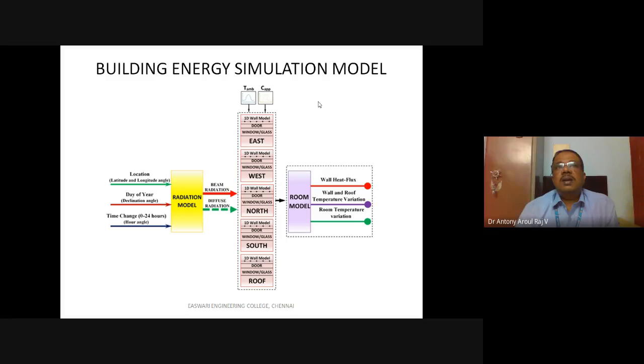So this absorption component will be by the process of conduction. For that we are generating the nodes and trying to capture the temperature distribution in the glass. And that is how for glass, even for a door, we can go for FDM solutions.